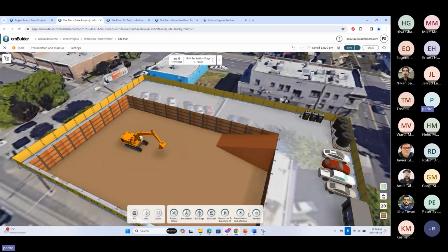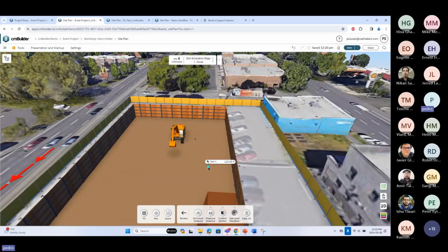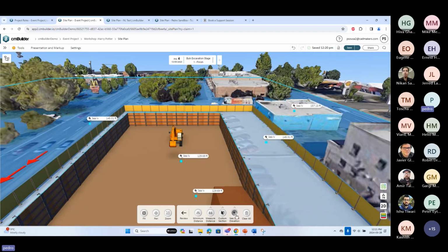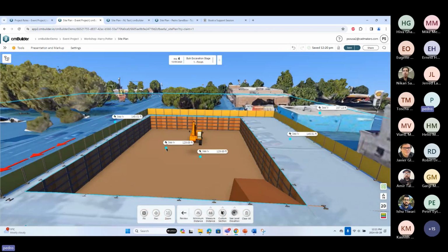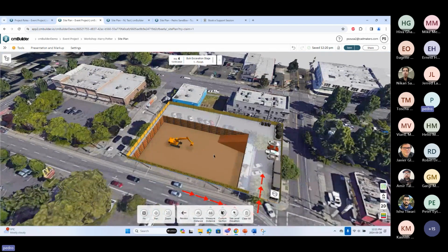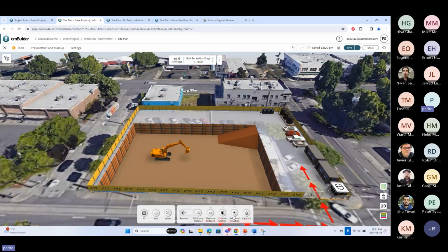So going on to the next one, the sea level elevation measurement. This one will allow you to define what the sea level is for a specific point. And you see that the value keeps changing as I move, so it's measuring in real time, but you can click to add a measurement at a specific elevation, right? This is good for understanding these elevations, but also to measure if the terrain that was created by default is accurate enough for you to work, or if you need to do any adjustments using the custom terrain tool.